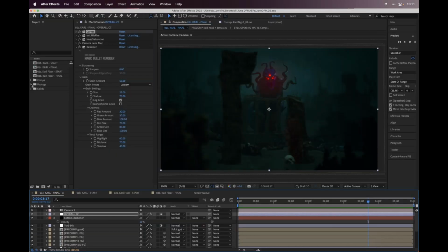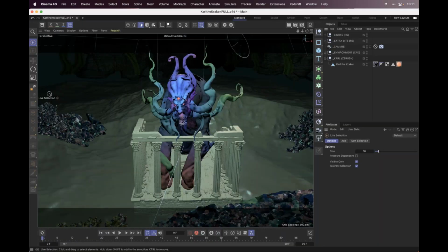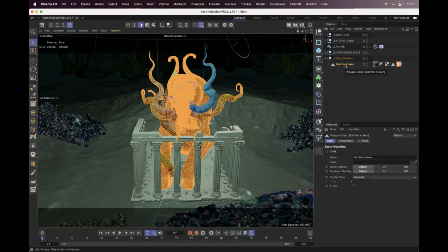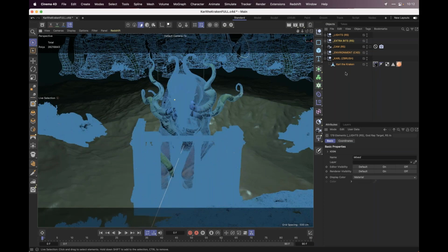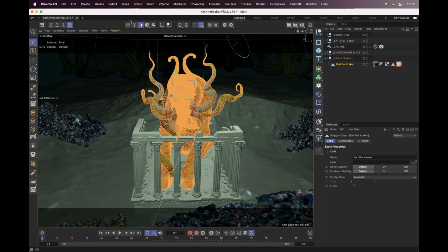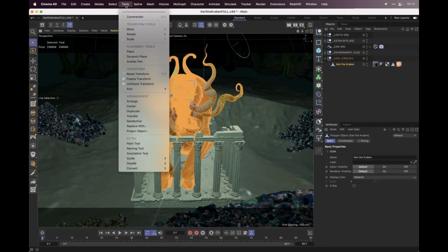I could have shown that there's a different way that you could do that. Oh, okay, teach me. What you can do is convert what are called polygon islands to objects. Then it would give you all of the individual islands as objects. Can you pilot me through that right now? Yeah, like if you select, okay, I'll select, and then you go up to, oh, this is going to test me now. Oops. No. Is it tools at the top in your top menu? Tools. And then at the bottom, convert.